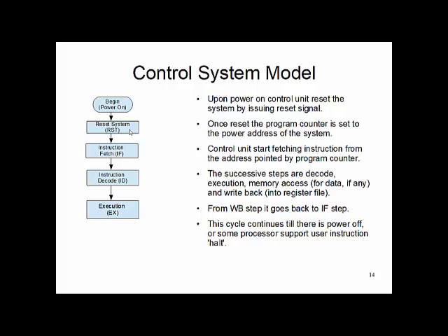Okay, and then the next cycle is memory access. Now this is a very specific step, and not all instructions need a memory access. If an instruction needs a memory access, meaning to store data or load data from the memory, then only this step will involve the memory component, and the controller will send the instruction to the memory with the address and a certain read or write request.